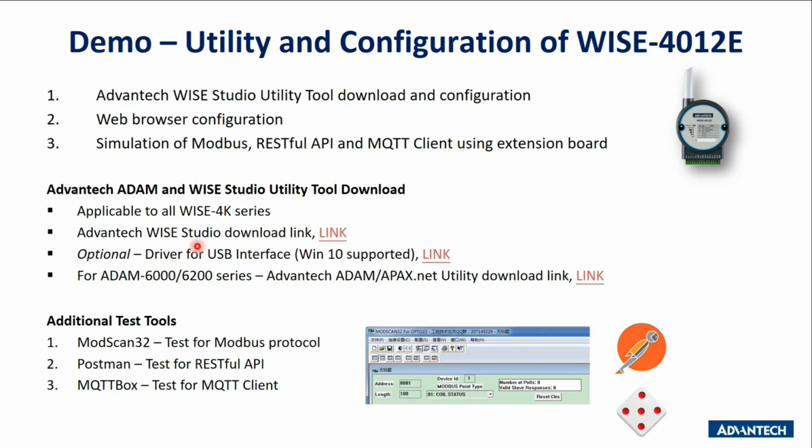Right. So some of our voice modules have a micro USB port to do the configuration. For that case, you will need to install a USB driver, because this USB driver is mainly used for converting the USB port to the UART port. Actually, this is one of the virtual COM ports used for COM to UART communication purposes. You really need to install the USB driver. This is optional, right?